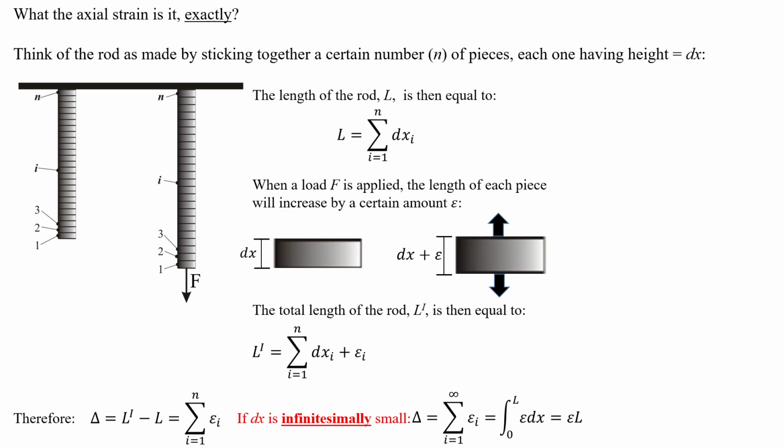So essentially what we're saying now is that delta now equals the sum of strain dx after you've formalised it. However, I can simplify that down again, and write it as strain times L. So delta, once I go through all of these steps, can just be simplified as strain times L. So that's the part you want to remember.